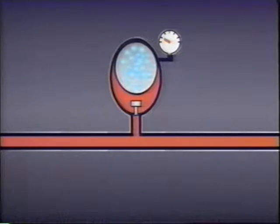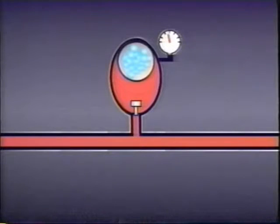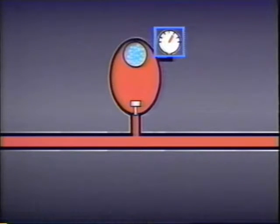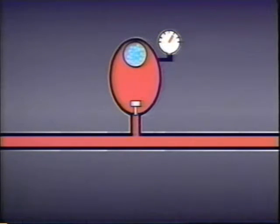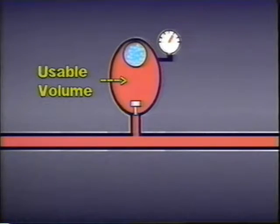To develop flow or to maintain fluid pressure, the accumulator must be filled with fluid until the nitrogen pre-charge reaches a specific maximum pressure. Then, as the system requires flow or pressure, the accumulator discharges fluid until the pressure of the pre-charged nitrogen drops to a specific minimum level. The volume of fluid the accumulator discharges between a maximum pressure and a minimum pressure is called the accumulator's usable volume. The usable volume depends on how quickly the accumulator is filled with fluid, how rapidly it is discharged, and on the pressure of the pre-charged gas.